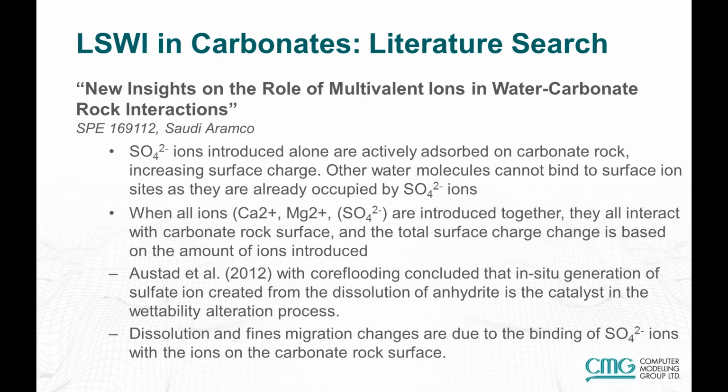Then Ousted concluded that with core flooding, the in situ generation of the sulfate ion created from the dissolution of anhydrite is the catalyst in the wettability alteration process. And dissolution of fines migration changes are due to the binding of the SO4 ions with the ions on the carbonate rock surface.